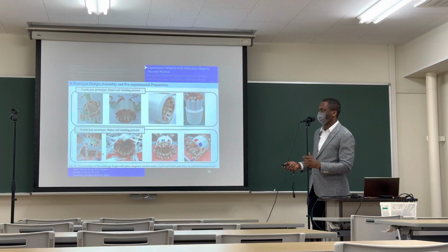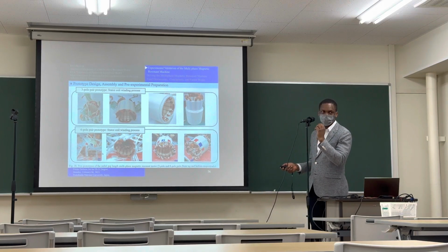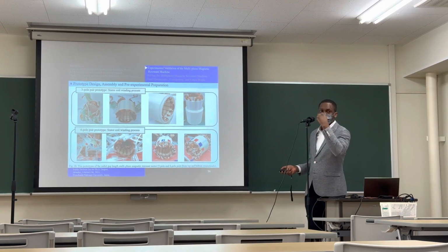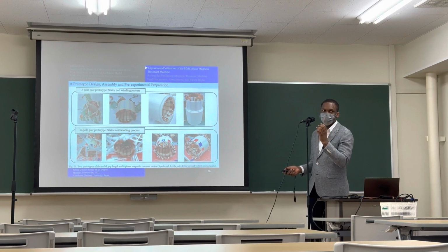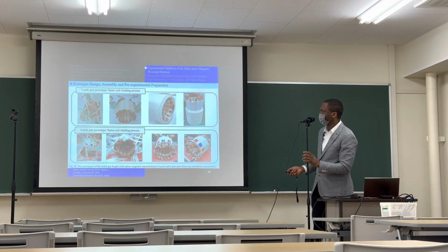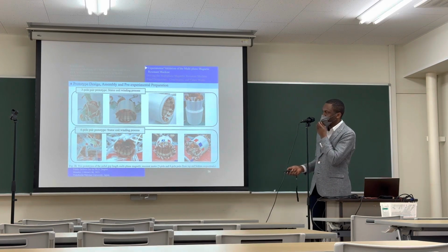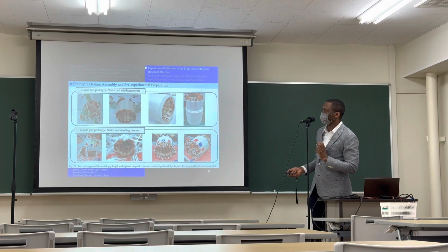For this 6-pole pair prototype, the winding process was really challenging because all the wires are in space. For this one we do 10 turns. We use 40 strands of wire and turn it around 10 times, so we have 400 strands. Each phase here has 400 strands of wire. And since we have two that come in one whole shoe here, you have 800 strands of wire that you have to put in place.